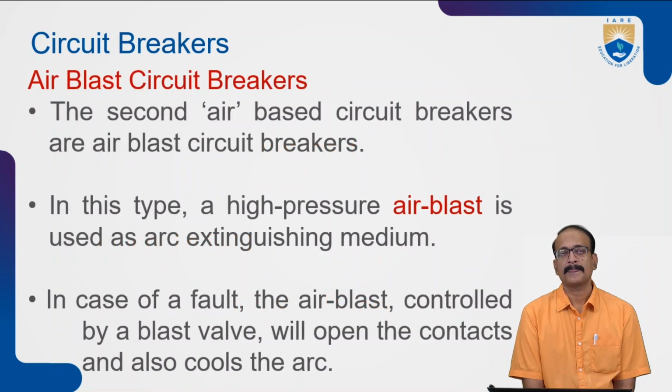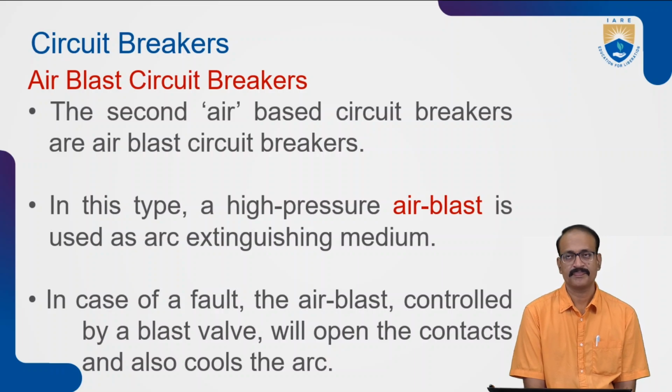So what is happening? In the air circuit breakers, the first is air magnetic, where we use a series of plates to divide this arc into different small arcs, and it gets diffused.